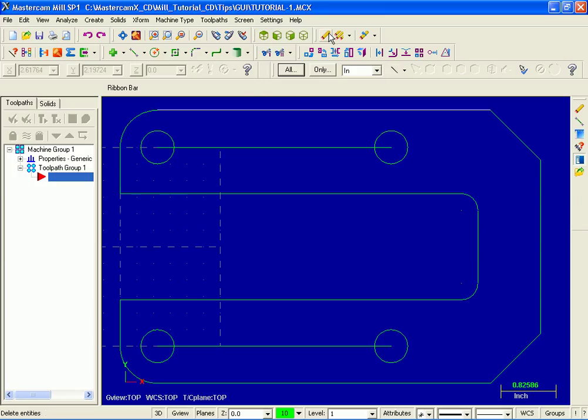Okay, I'm going to select Delete. And what I'm going to do is pick this entity down here, and pick this entity. Now maybe that last entity was a mistake. How do I unselect it? Just pick it again. So I only have two selected entities. As you can see, they're in yellow. Now the next step is to move up and hit End Selection.